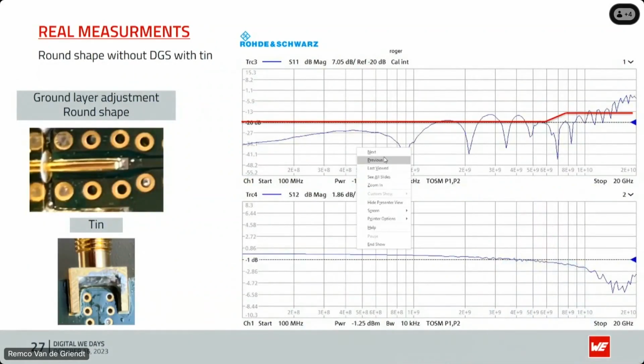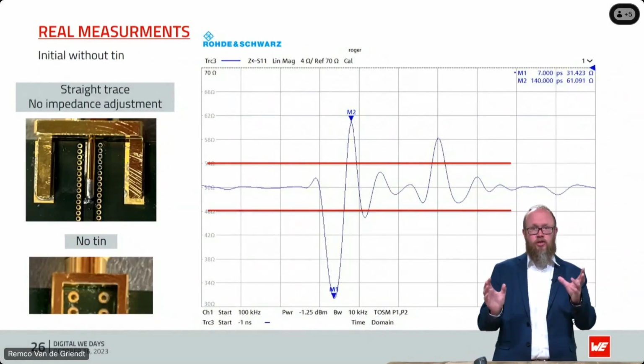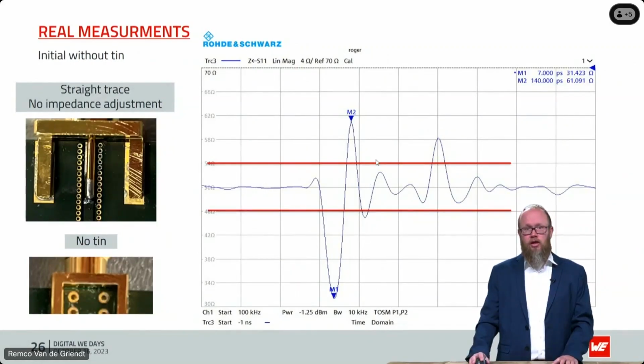If you look at this one, here first you have the coaxial cable, then you see the first connection to the PCB, to the connector itself, then you really have a big dip, and that already affects how everything is going to travel because you have no grounding planes there. Then you go over to the PCB. Normally you must have a straight line here like the coaxial cable, but with this one you really see a big variation in impedance, and that's why you see it back that way. This is the second connector.